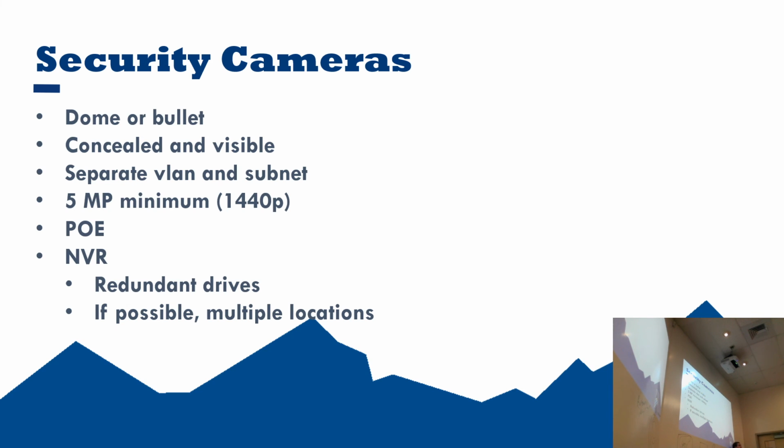Definitely use PoE to power them. There's no reason not to use PoE unless they use a ridiculous number of watts, which is unlikely. If you have an NVR, store the footage on the NVR. Definitely you want to have redundant drives, that sort of thing.